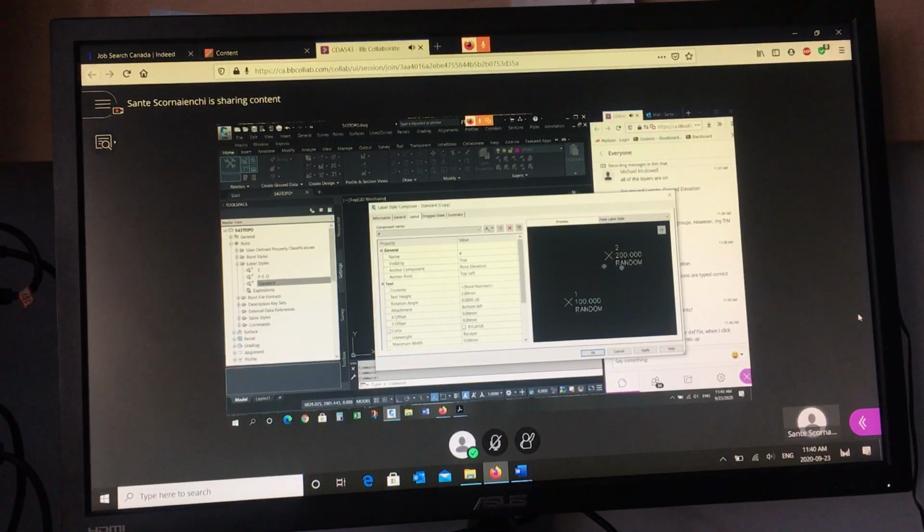If you go to the layout tab and you want to turn off one or all of these, you have to scroll through this component name. So the number, if you turn that to false, it turns the number off. If you go to the elevation and you turn that to false, it turns the elevation off. And if you go to point description and you turn that to false, you'll see nothing. So this is where you make those three different visibility states. So it's in the layout tab. Okay. Does that help?